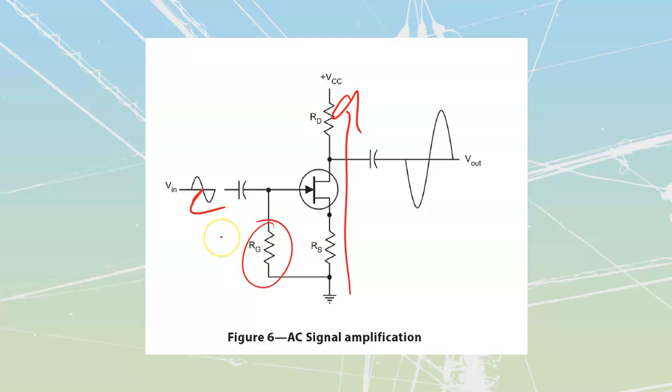This path that we see over here, this resistor, can be very high, hundreds of K ohms and more. So we're only going to have a tiny, tiny amount of current travel through it. We do need that complete path. We will have a tiny, tiny bit that's going to go through, but it's nowhere near the same as what I had on my BJTs.